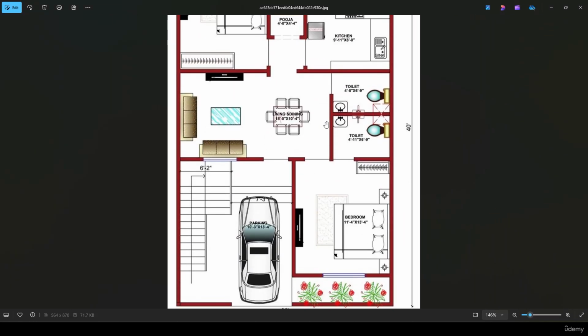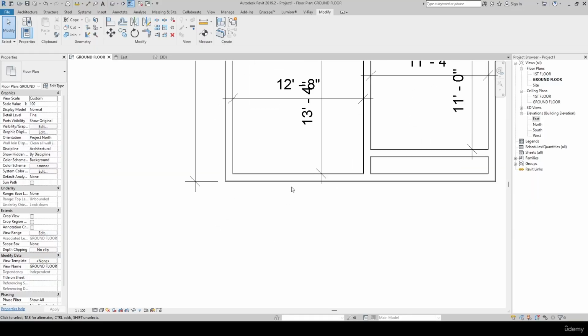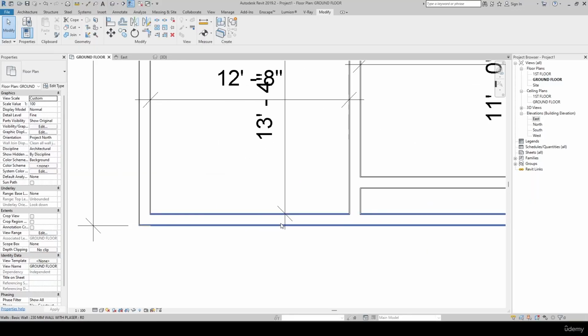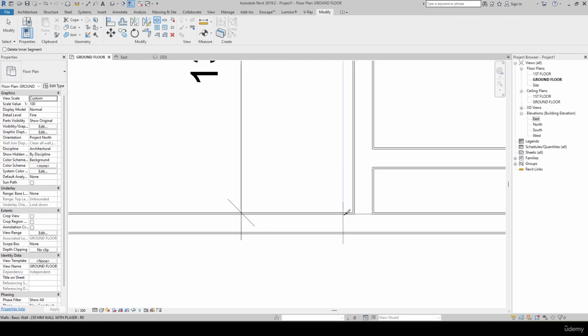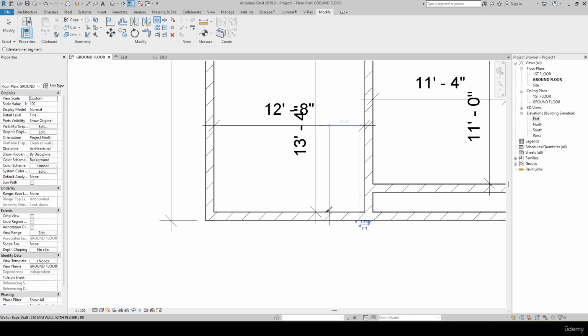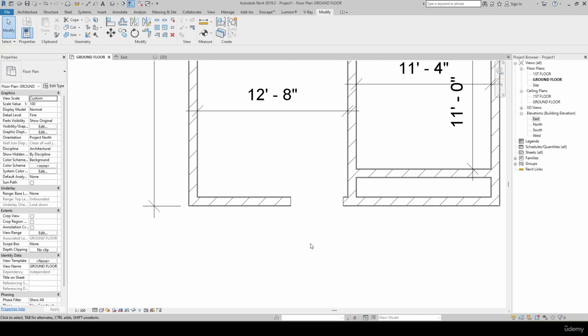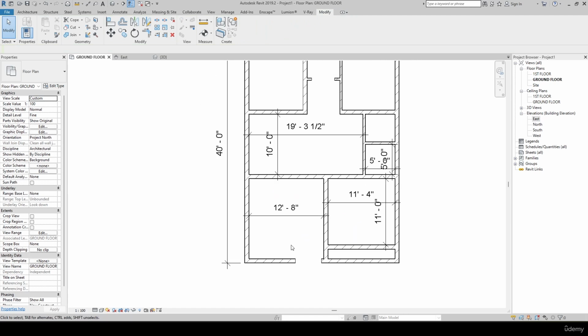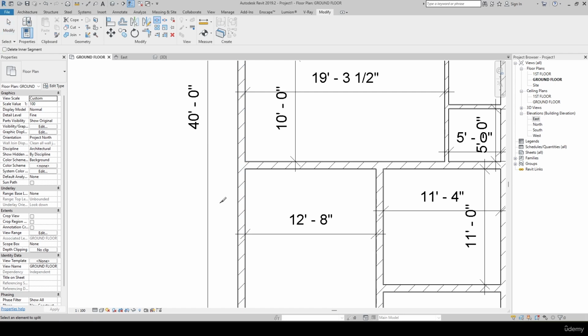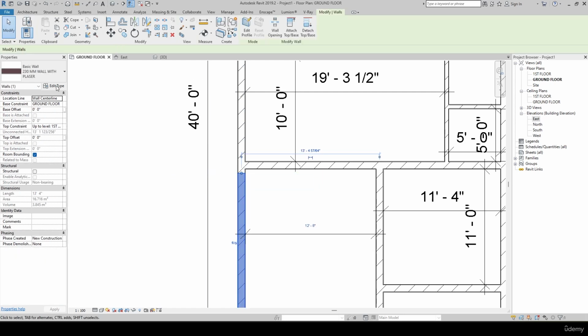In the front I think we need to open here. This is right, I'll open this here as well. I'll use the command split, SL. I'll take around 100 mm extra somewhere here and I'll open this much. Okay, select this and I'll delete, and I'll split from here itself, SL. Okay, this entire wall I'll make as a duplicate.